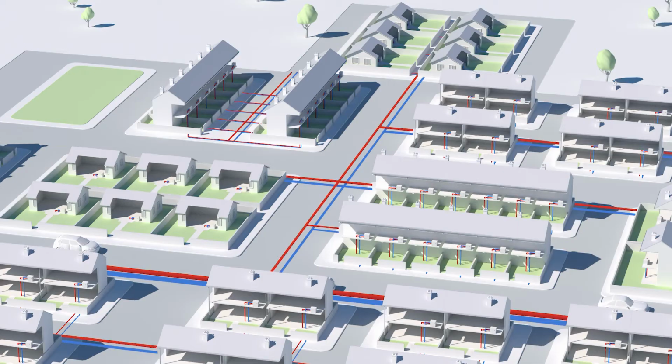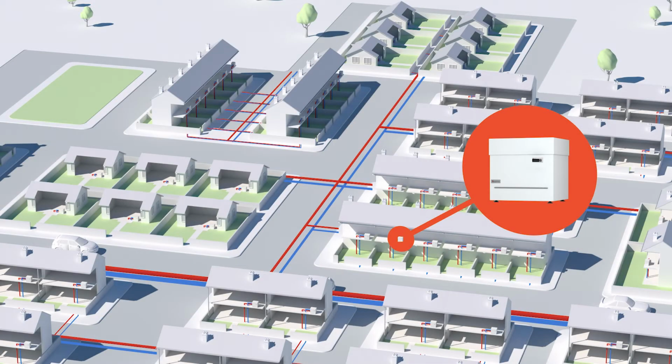The foundation for this vision is a type of district heating called an ambient temperature loop. This consists of a series of pipes in the ground that deliver a working fluid, typically between 0 and 20 Celsius, to every property, domestic and commercial. Connected to this network are heat pumps that upgrade the temperature you need for heating purposes and hot water, and downgrade it, chill it, for air conditioning and cooling purposes.